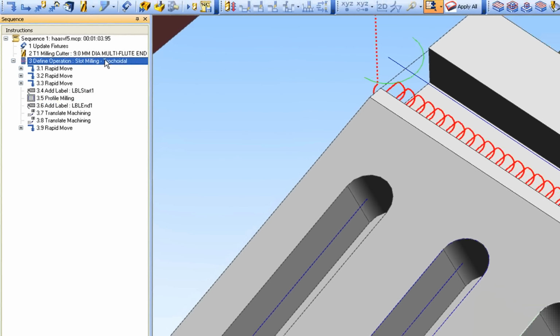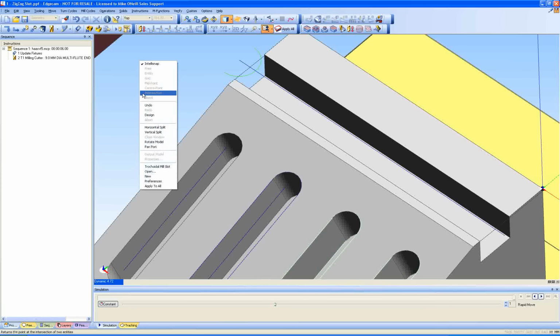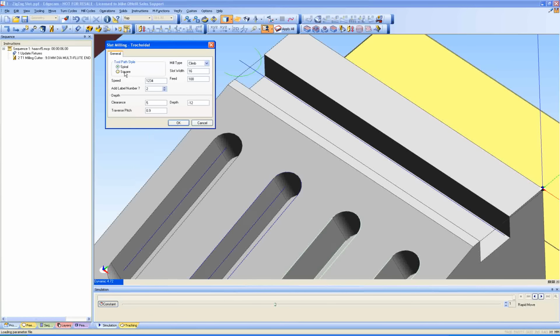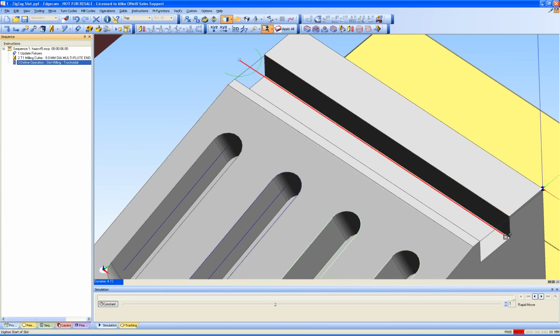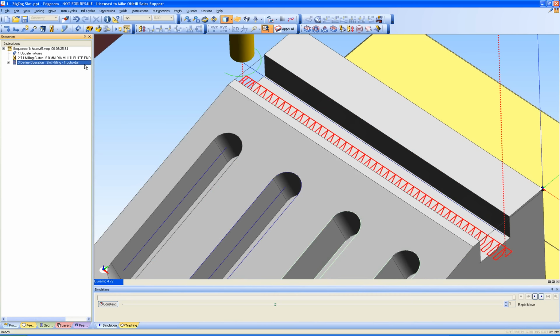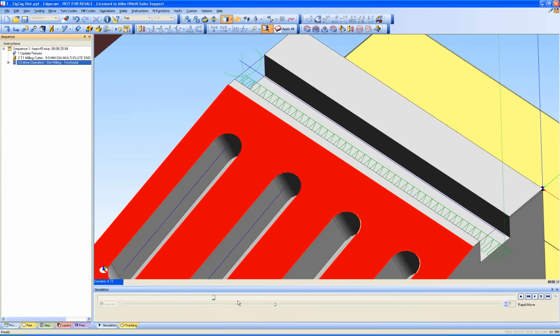Let's just clear that and just do another, just show you the other type of effect that you get with trochoidal mill slot. That's a square pattern. It's very much like a dog leg or a crabbing action, where it uses a square motion to cut the slot. This time I'll just digitize in the opposite manner, and you'll see how it crabs away using the pitch, going to the depth along that particular pattern. Let's just speed things up a little bit again.